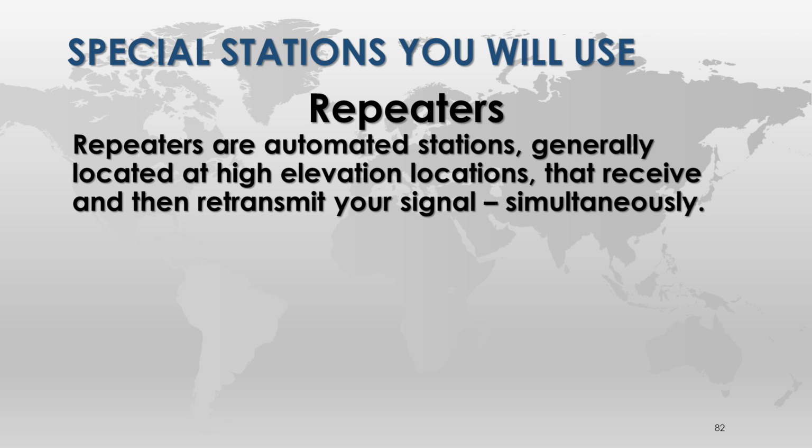Make sense? No? Okay, I'm transmitting on this frequency. It is offset a standard amount, and for 2 meters, it's 600 kilohertz. I'm listening on this frequency. The frequency I'm listening on is the one that I'm reading on my readout. When I transmit, it shifts up 600 kilohertz and transmits higher up, or lower. It could be 600 kilohertz.